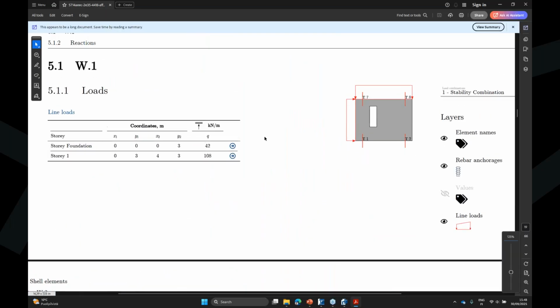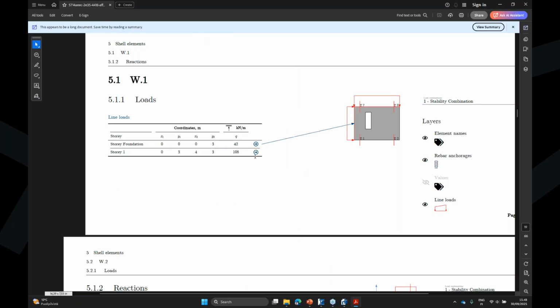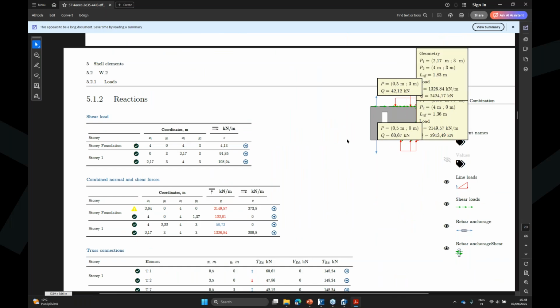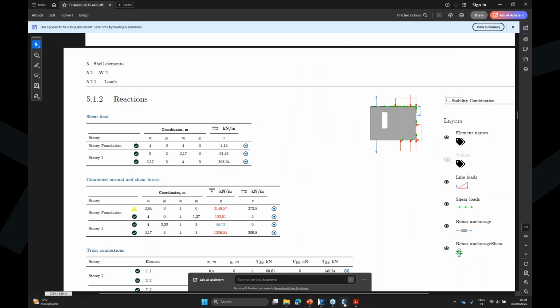So you can now take this one paper and give it to element designer, and he can design the wall, because you have dimensions, you have a mass, you have a strength class of concrete, you have tension anchorage, location of those, and also loading, like how much is the compression, where the compression is located in the element. So you can design the foundations.